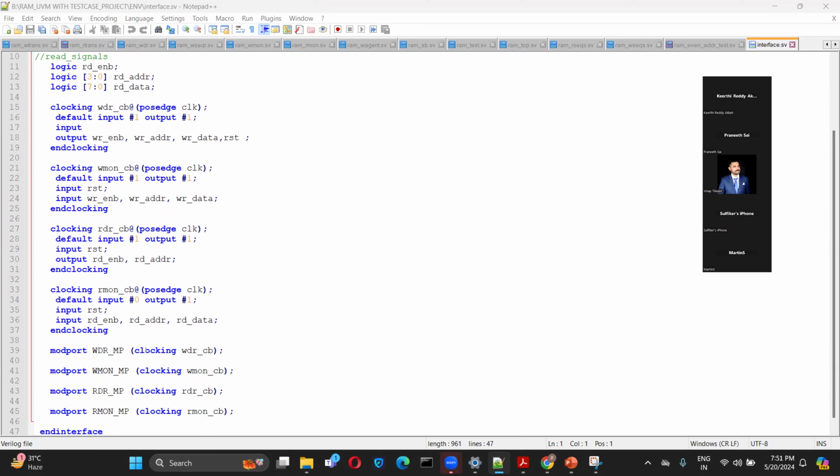For example, we have some race conditions, right? We have got solutions in SystemVerilog. In Verilog, we got a solution like non-blocking assignment: because of the different regions in Verilog, the non-blocking things will be assigned in one region and evaluated in some other region. Through this, some of the race conditions we can resolve. In SystemVerilog, how do we resolve this? Through one thing, a program block, and the other thing is also a clocking block. Basically, it gives us proper synchronization, having the input skew and output skew also.